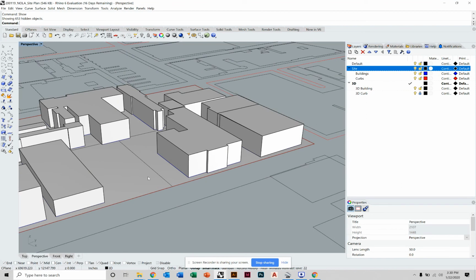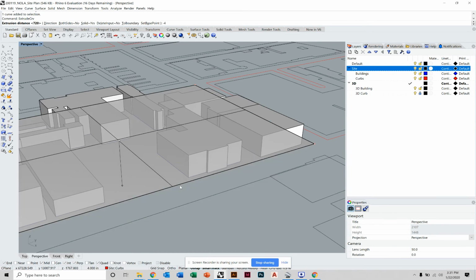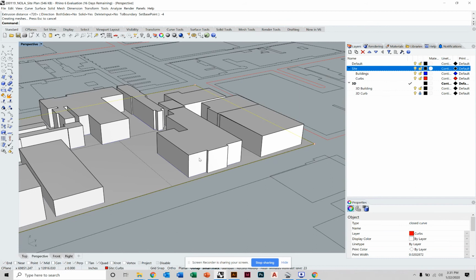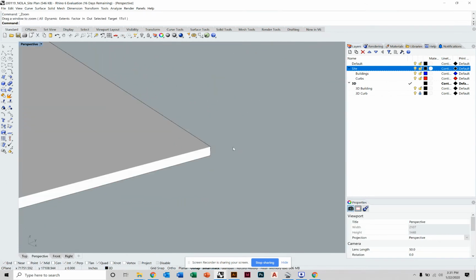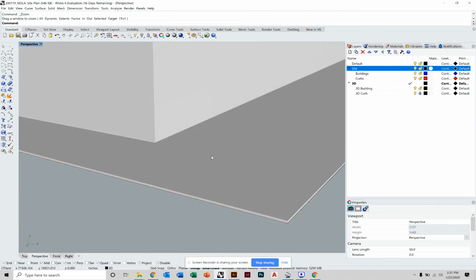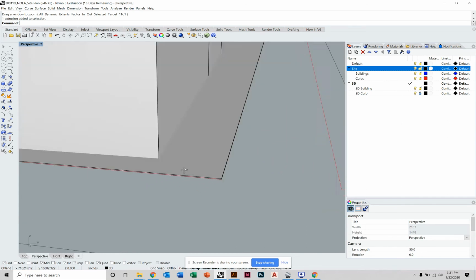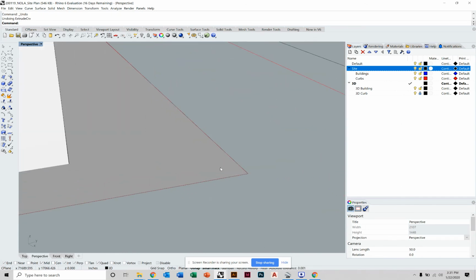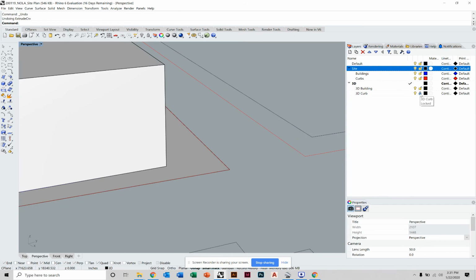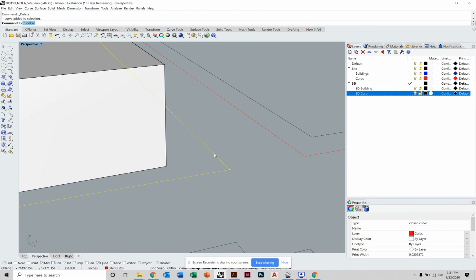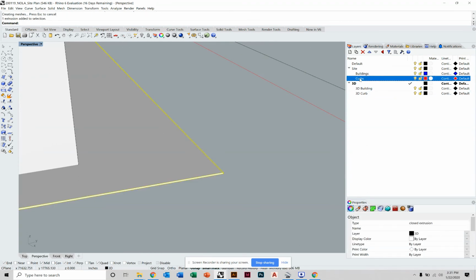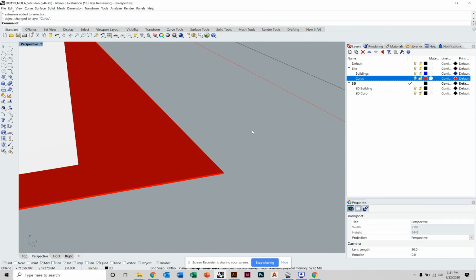And what I would do is, just so that the ground on the site is 0, I would extrude the curve down. So how do I do that? Extrude, and I do -4 is 4 inches down. So now I have some thickness. Okay, so I'm going to do -4 for the curve.